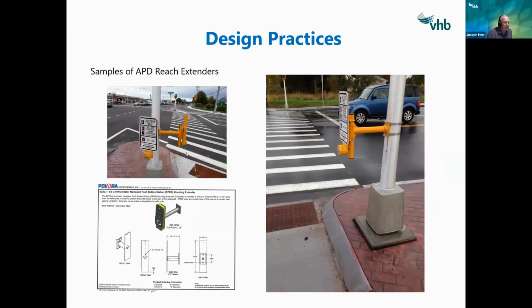Next is the extension reach. Usually during the inspection, we'll go out there, maybe do a plumb bob to find out where that lands next to the curb, and then do a lateral measurement to see if we meet that 10 inches. These extending brackets are different. Each manufacturer is a little different. There are some that articulate on more than one plane. They have the ability to go left, right, up, and down.